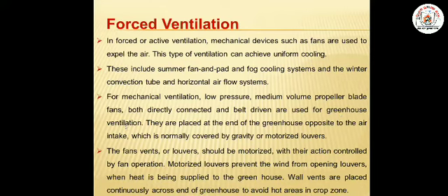greenhouse ventilation. They are placed at the end of the greenhouse opposite to the air intake, which is normally covered by gravity or motorized louvers. Here the fan vents or the louvers should be motorized with their action controlled by the fan operator.